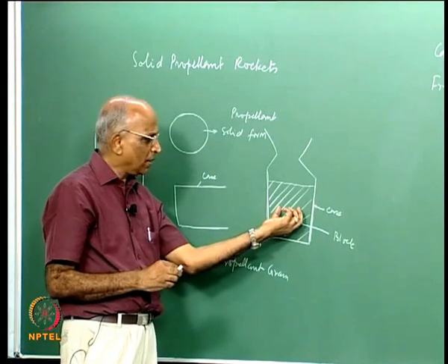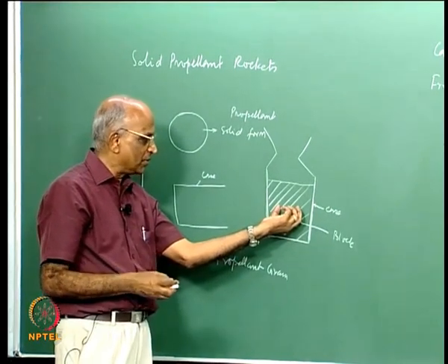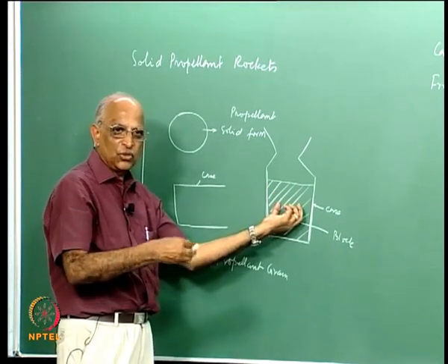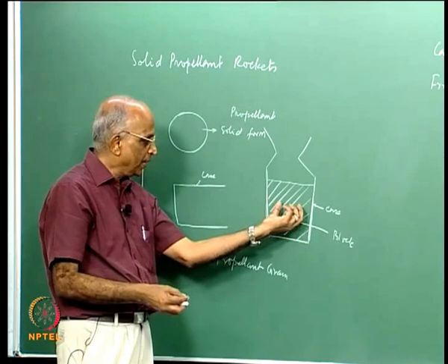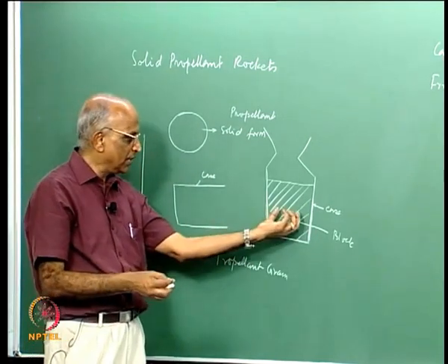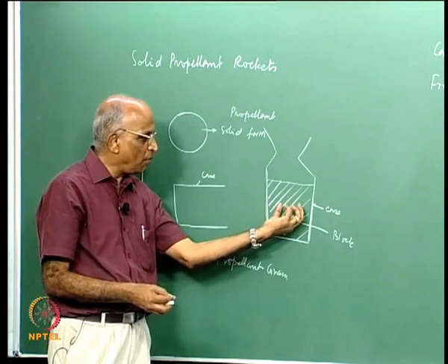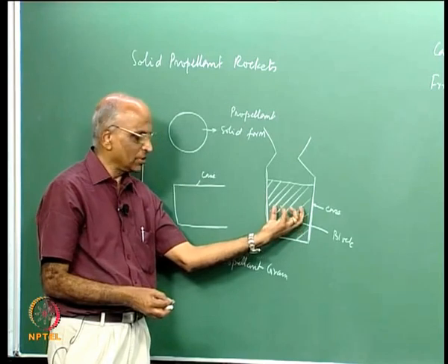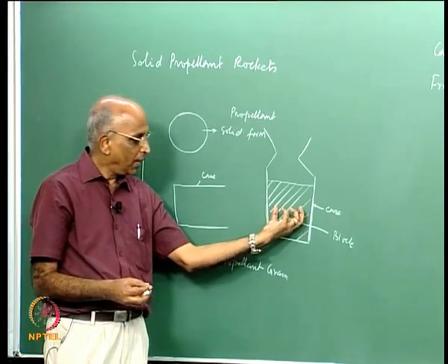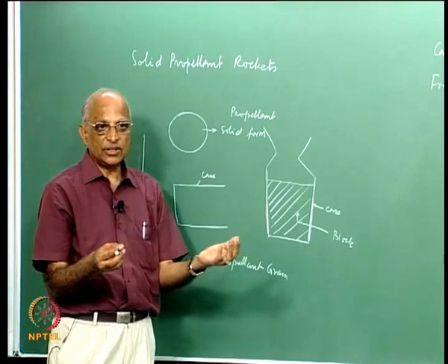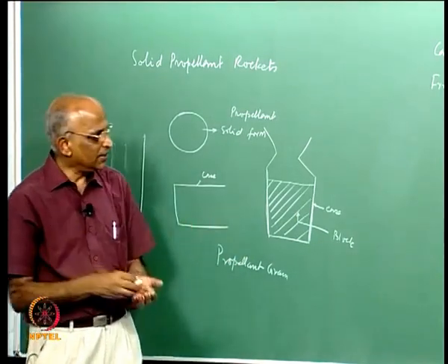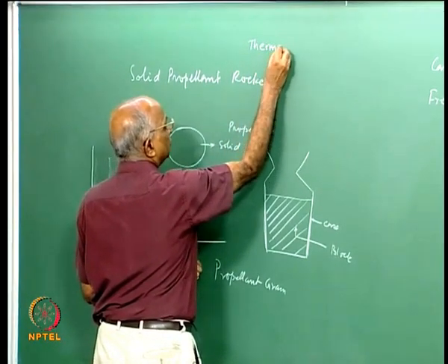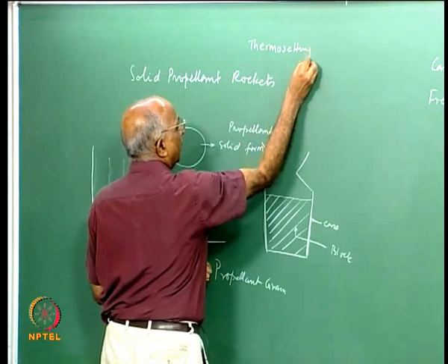Let us again look at the problem in a slightly different scenario, but before that, to repeat here, if I have a composite propellant, something like a polybutadiene, which is a resin in liquid form, I put into it the solid loading crystals AP and aluminum, I have a slurry, a mixture of all these things. I heat it to a high temperature, form a solid block, and this solid block, when it is inside a case, is what is known as a propellant grain. This resin is something that when heated it sets, and this resin is known as thermosetting resin, because when heated it becomes hard.